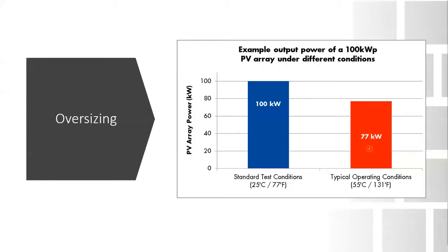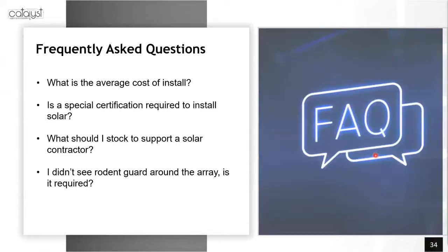And if they do, say a nice sunny April day like we're having up until today because it's snowing, but on the weekend we had some beautiful days, it was nice and cool, okay, so those modules may have produced their maximum. Worst case scenario, the inverter will just do what's called clipping. So it will never over output, and you will never overdrive it. But this is the real reason, because most modules will never perform to their standard test conditions. They'll perform to their typical operating conditions. And that's why we oversize. And that is solar installations, fast and info packs.